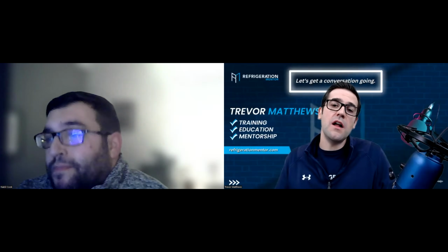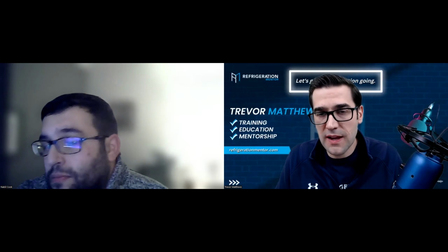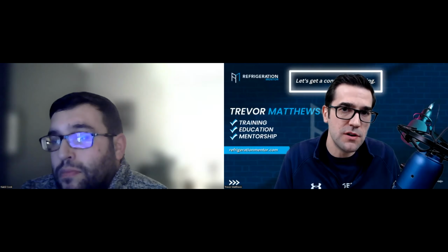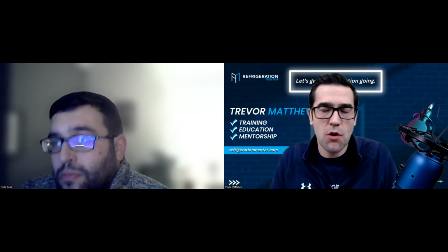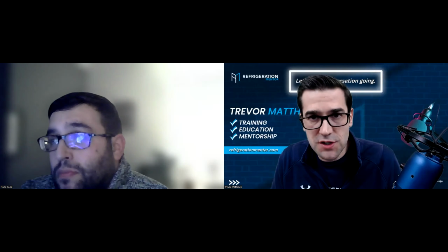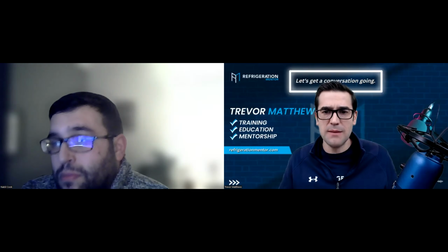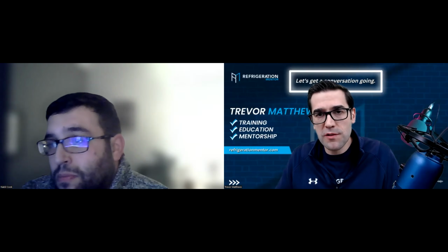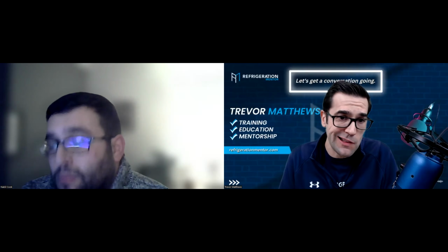Yeah. And that all depends as well, because depending on the compressor will depend on the range. So maybe one that has that modulation, that type of digital capacity control, because Bitzer calls it CR2, Copeland calls it digital, Frascold calls it Capiflex. There's lots of different names for them depending on the models, but depending on the motors themselves will depend on the range. So some can ramp down a lot lower than others.